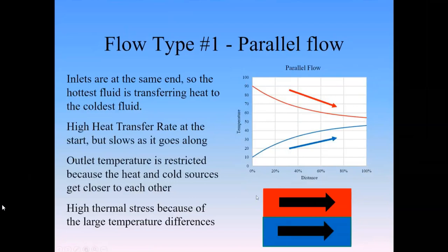This type of heat exchanger configuration tends to be a little bit more stressed. It sees a lot larger temperature differences, and that can lead to more stress, so thermal stress.